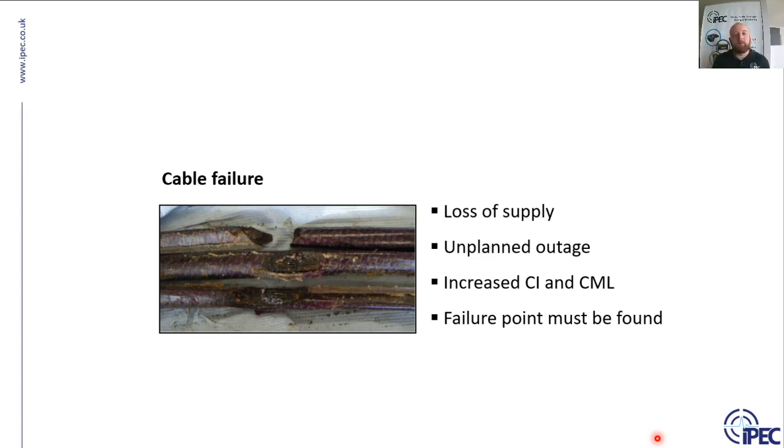So naturally you need to find where that cable has failed with fault location technology in order to then conduct the repair to bring that system back online. Now with underground cables, that can be very problematic depending on where the cable actually fails. Last minute requirements, in London for example, we can get a 24-hour repair order, an emergency repair, quickly shutting down a road, digging the road and repairing the cable. Still very costly, still very inconvenient, if you like, for the wider application.